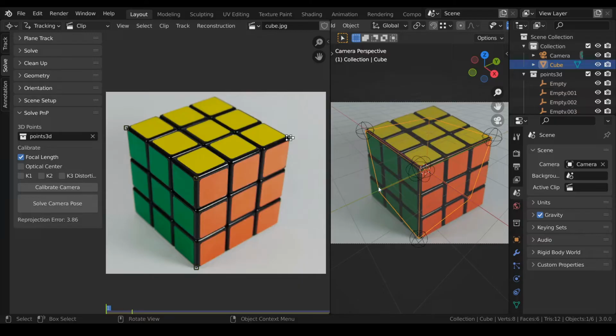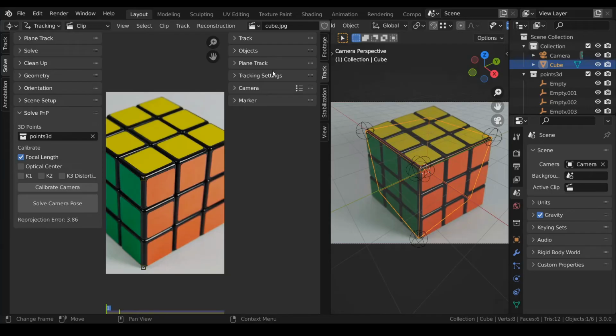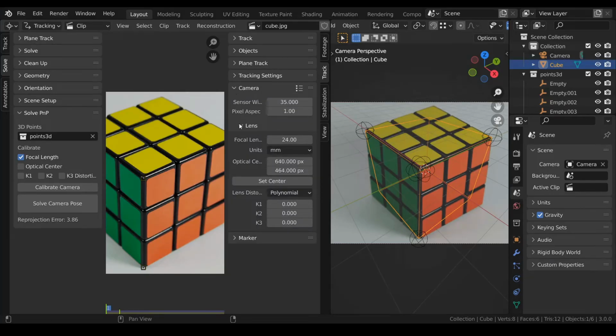The add-on also provides the option to attempt to calibrate the camera intrinsics. However, to use this feature, we need at least 6 points. The more points, the better, especially if you're trying to calibrate more than one single camera setting at once. You can find the current camera intrinsics under the lens parameters of the clip camera. In this case, the image mismatch is mostly because the focal length is off. So I will add a couple more points and try to fit the focal length.